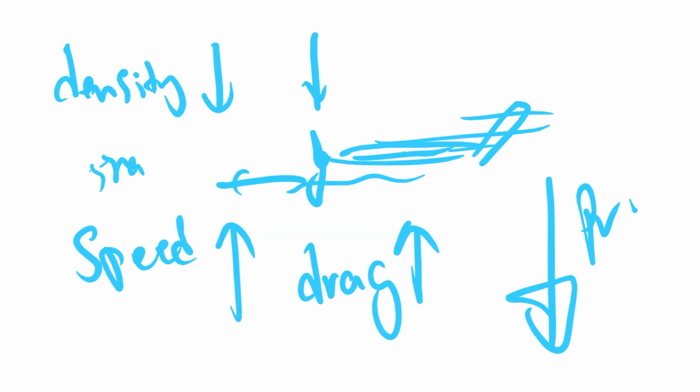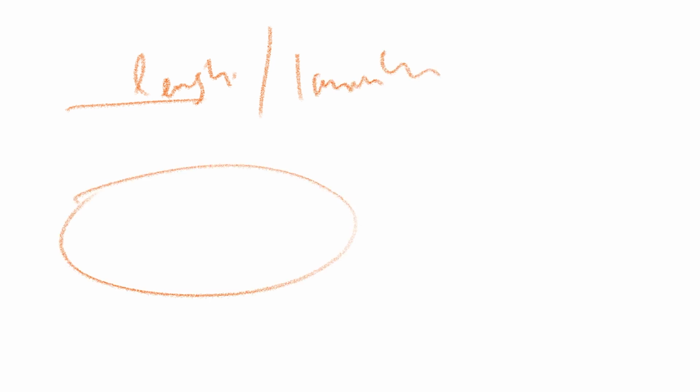So what are the other things that we need to consider? The other things that are important as the remote pilot in command are the length of the runway available, or the launch area. Suppose that you are going to launch your drone, then you have to consider the area available, right? So that you are operating this drone safely.